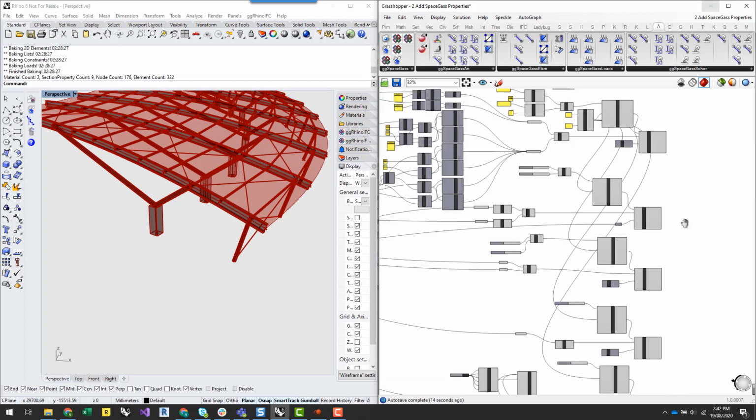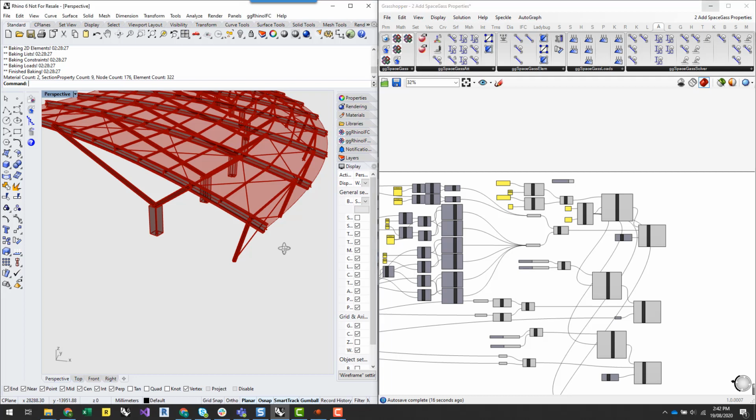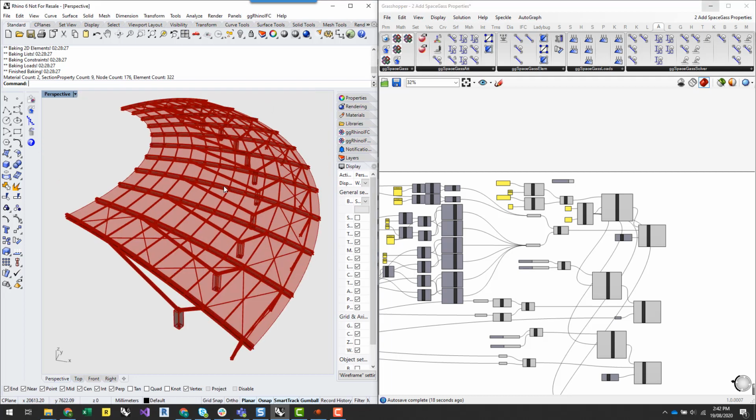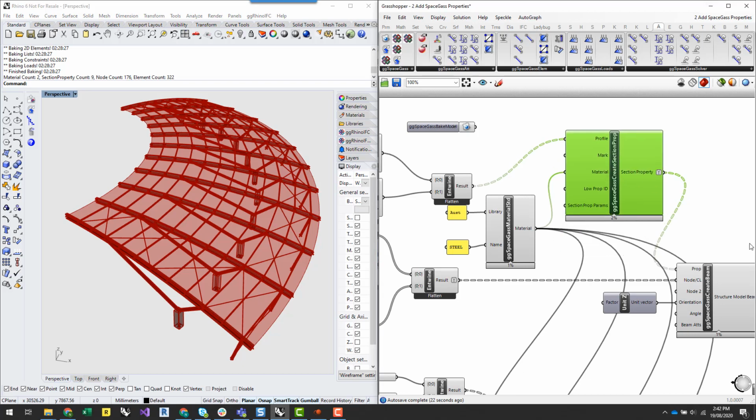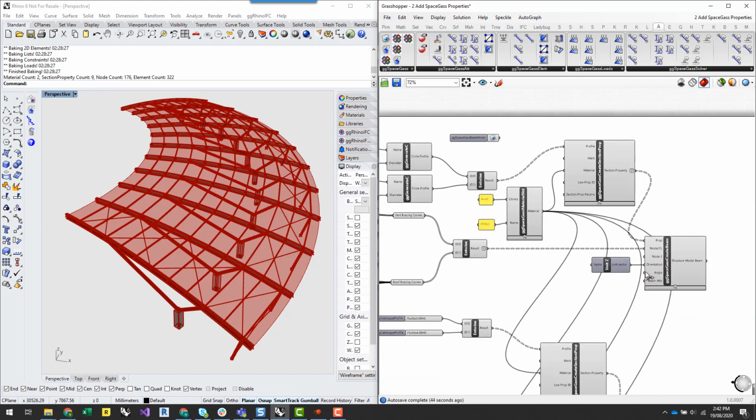Right, so now that we've added our restraints, I'm going to go back. Currently in the model, the default is that a member will have fixed end releases. Now there are obviously a fair few members here which are going to be pin connected, which means we're going to want to make sure that we specify those releases as pinned.